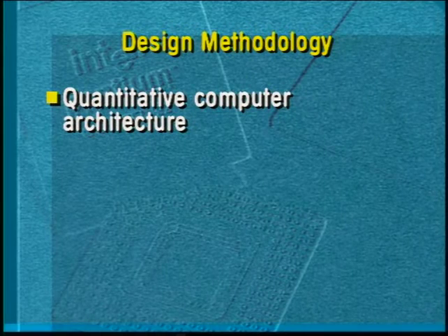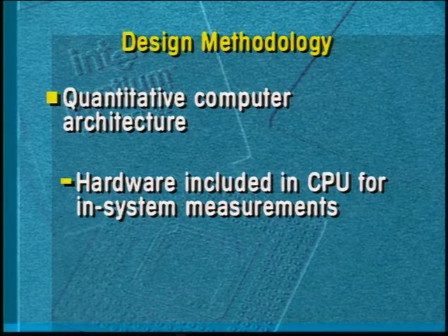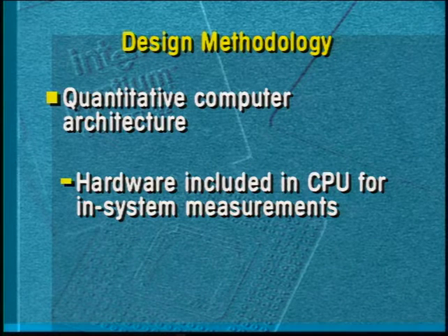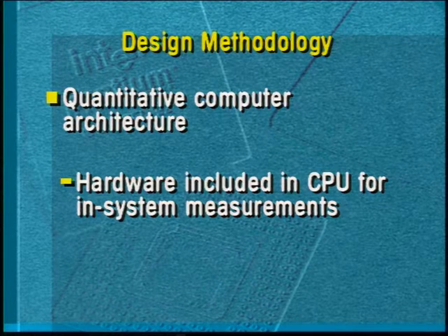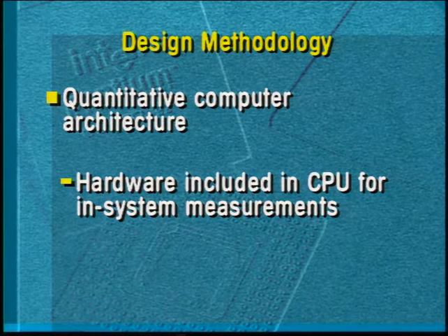The results of this trace-driven simulation gave us some quantitative feedback on the value of the different aspects of the hardware and software. We even carried this quantitative computer architecture into the hardware itself by providing a number of facilities within the processor to support measurement of running systems, so that we have a very nice event monitoring facility that can count both discrete events, such as cache misses, as well as some duration events, such as bus stalls. Later on, we'll see how we use these performance monitors to measure the effectiveness of some key microarchitecture techniques included in the Pentium processor and how they performed when executing the SPEC benchmark suite.